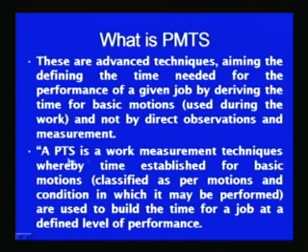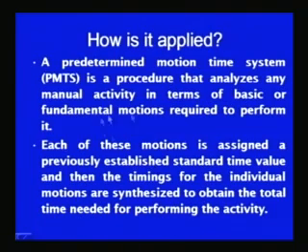The PTS is defined as a work measurement technique whereby the time established for basic motions is used to build up the time required for a job at a defined level of performance. So, these basic motions have been defined and categorized in different ways in the different PTS systems which have been developed.